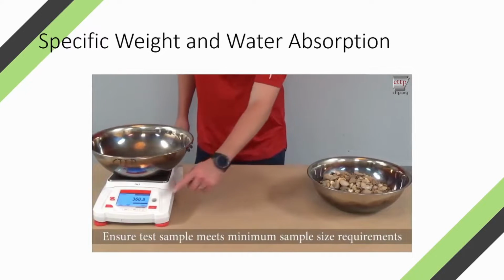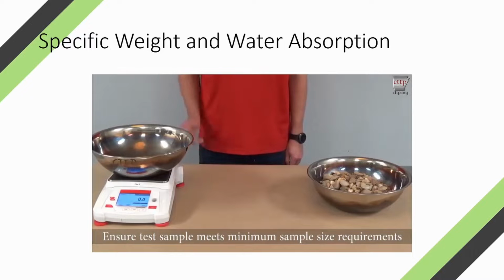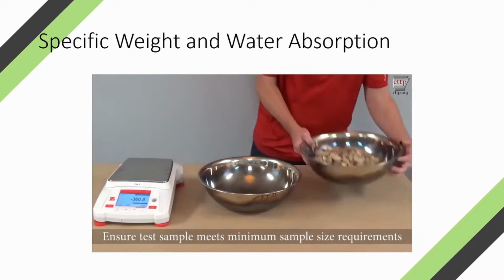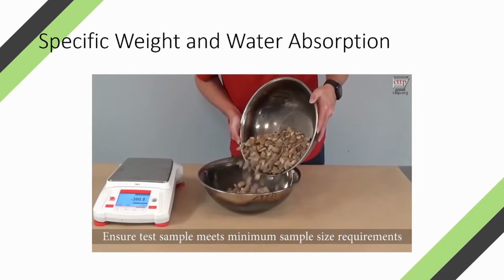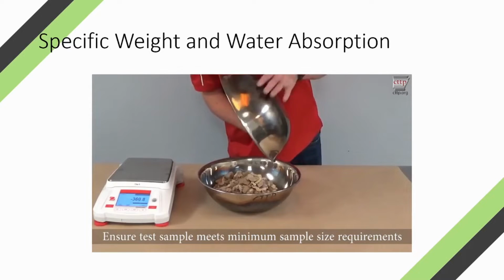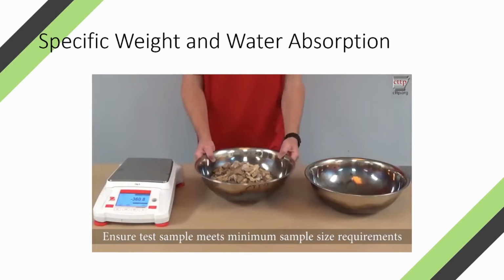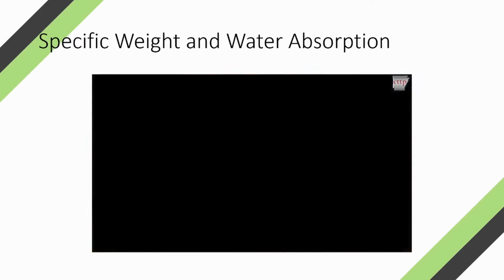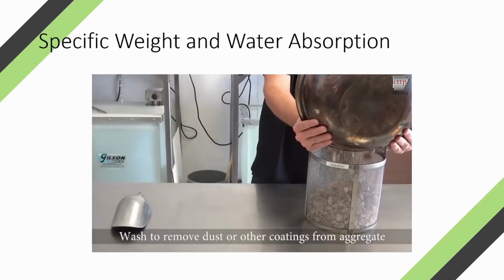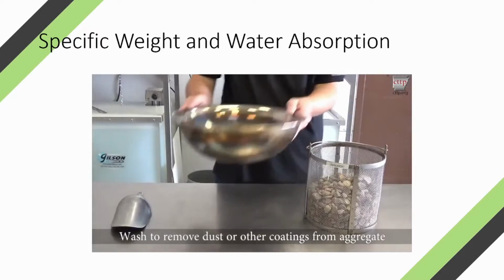Ensure that the test sample meets minimum sample size requirements. Wash the sample to remove dust or other coatings from the aggregate.